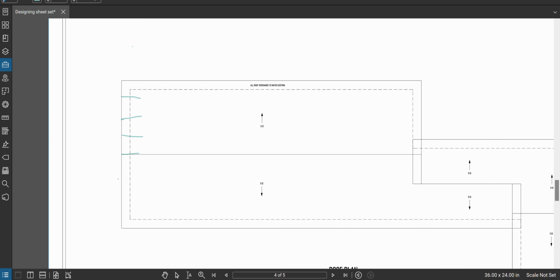Basically what I want to make sure is that when the wind blows up on this wall and tries to push the roof off, these outlookers aren't going to get ripped off. So I have to check some tables and things in the Wood Frame Construction Manual as well, and I can go into more detail on that in person or on a Zoom call or something, but not in here. So that's how I would check those things.